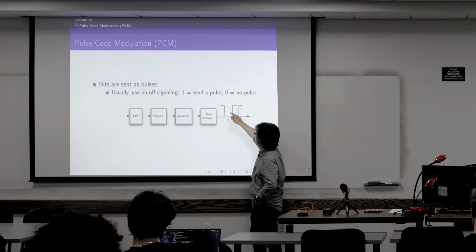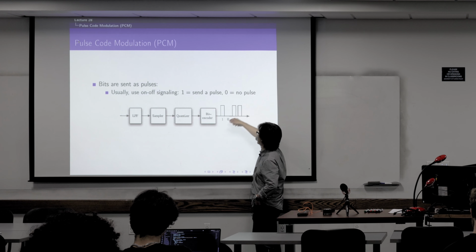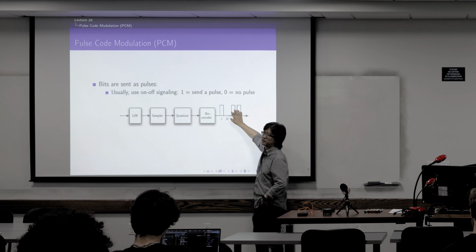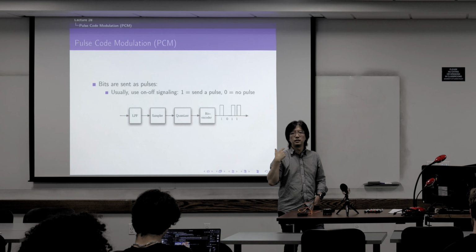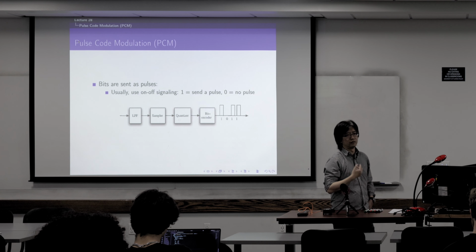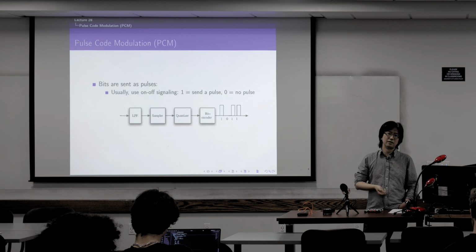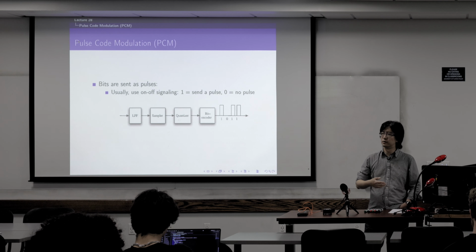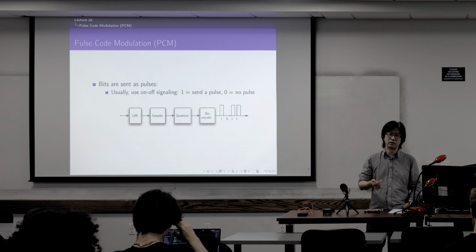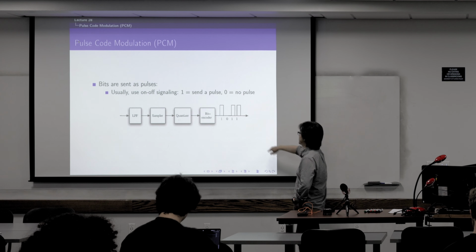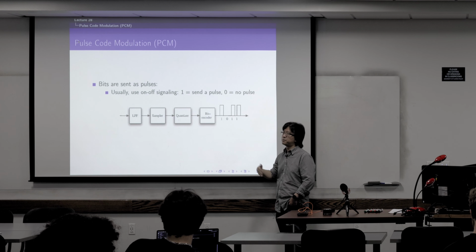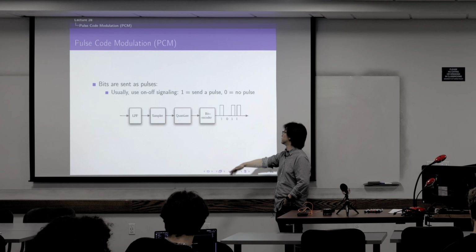Right? Before, we just had this kind of analog signal, but now it looks a bit nicer. And then all the modulation schemes that we used before can be used here. We can use DSB-SC or DSB no SC, or VSB, SSB, USB, or LSB. Hopefully you still remember those, QAM. We can use everything that we learned so far to transmit those, without big difference. So now we know how to transmit those already.